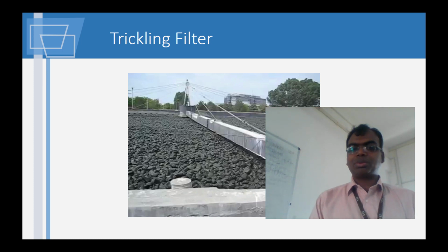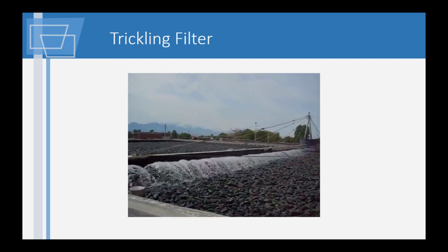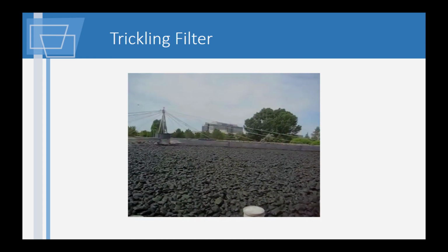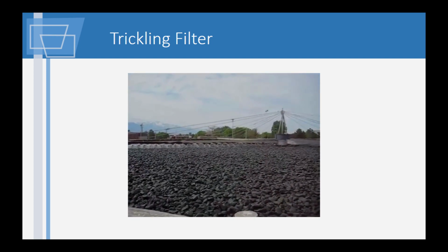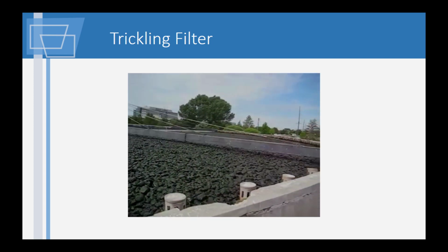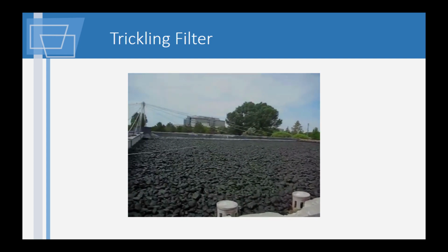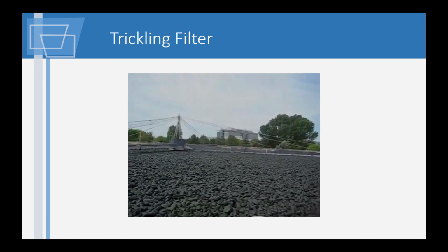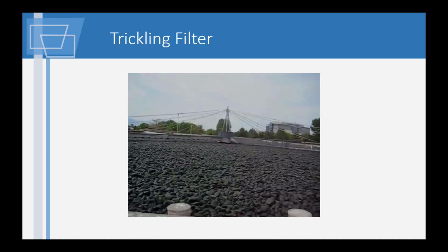Okay. So here there is a system. Just see, this system is working without electricity. These were part of the original design of this plant. This plant's been upgraded a couple of times since it was originally constructed. It's pretty amazing to me to see all that big steel structure right there. There's no electric drive turning that around or no motor. That's all spinning just from the water, there's enough water pushing it around. Really? Yeah, that's pretty amazing, I think. But at any rate, the rocks in this trickling filter are about 6 feet deep.